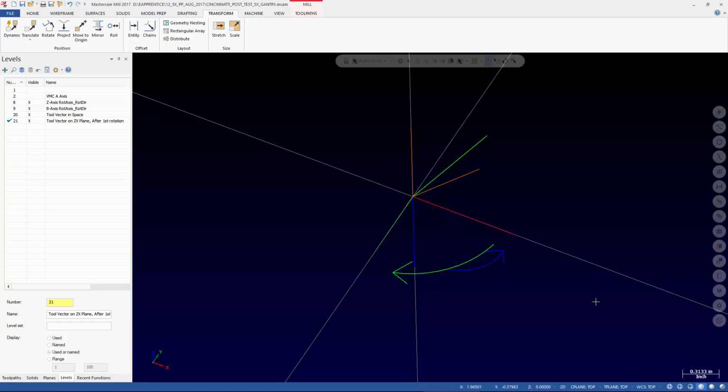So go out to the machine and drive it in the manual jog mode, drive it in handle mode, and drive it in MDI. Make it position and go to different rotations, and that will help you discover, along with the manual, what the limits of the machine are. Because once you get the vectors set correctly, the rest of the stuff falls into place really easy.